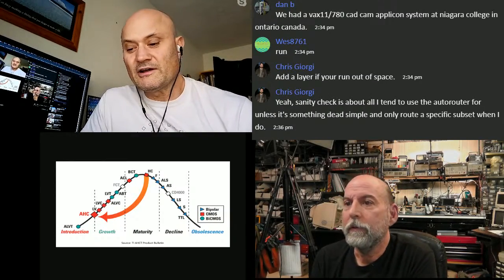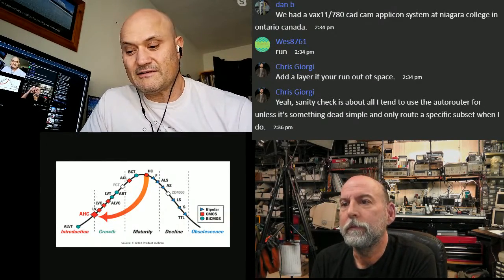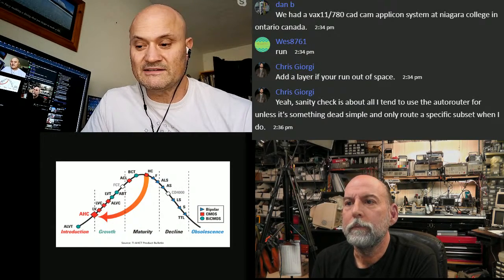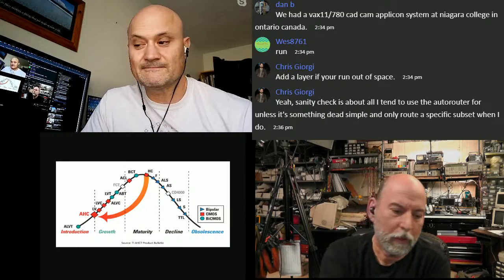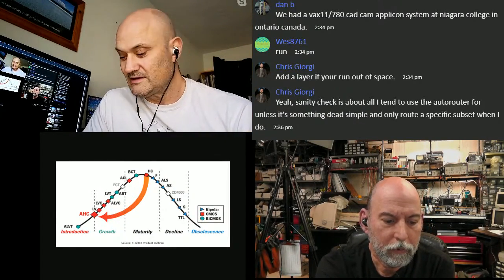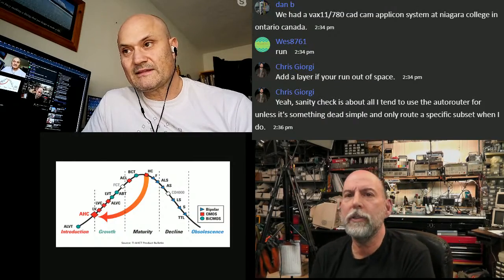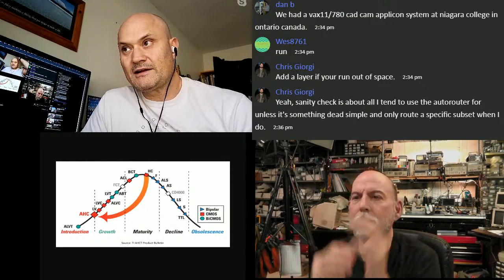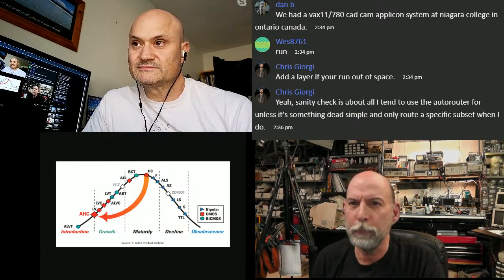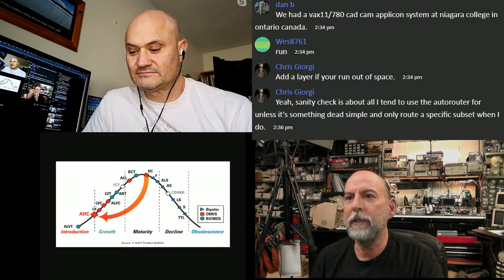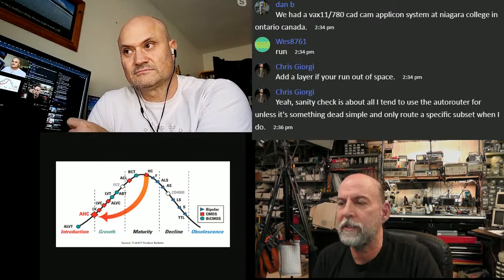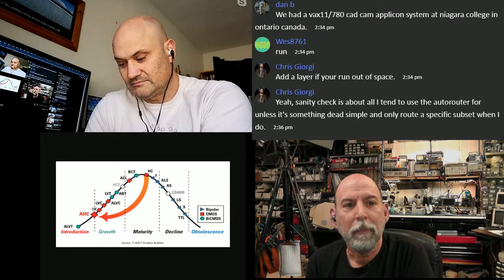I agree, a lot of the routing technology out there makes ugly results. But if this thing's going inside a box and it's not going to be noisy, I don't have a problem. No one else is going to see it. I'll know, but the other problem with auto routers is if you have laid out a power ground grid first, you have to tell it to leave it alone or it'll go in, remove loops, do things like that. So you want to lay in your foundation, but then you want to tell the auto router to build on top of it, not tear out the foundation.